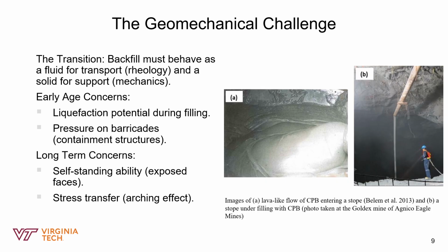The second is the long-term concerns, which is after the fill has cured and hardened. Here we worry about the self-standing ability. Eventually we will mine the rock right next to the fill, and we need to make sure that when we blast that rock away, the exposed backfill is strong enough to stand vertically without crumbling.